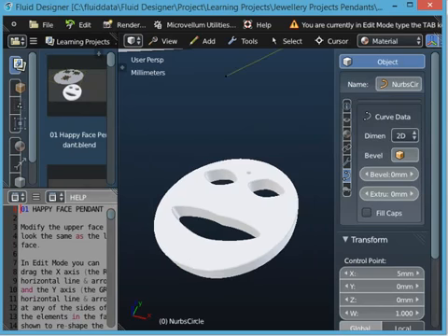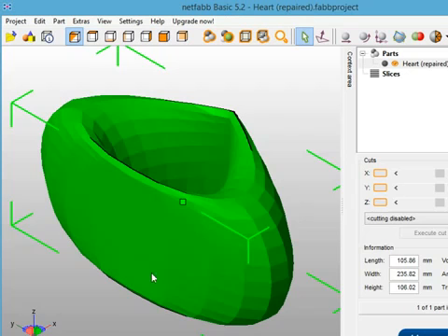What we always recommend is that any object that you create in Fluid Designer, you always export it as an STL or an OBJ file, and always import it into a mesh repair tool called Netfabb Basic. Netfabb Basic will fix any problems that Fluid Designer gives you.